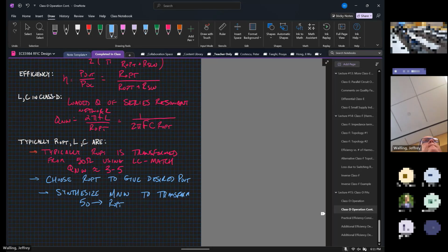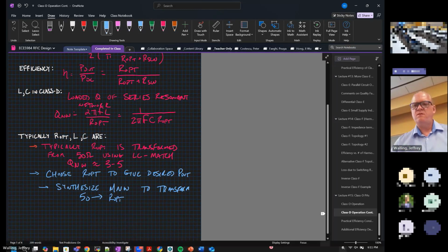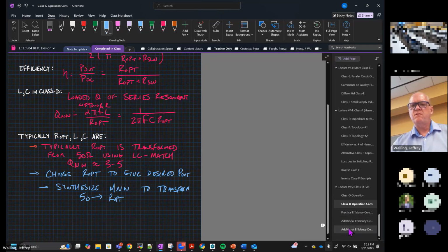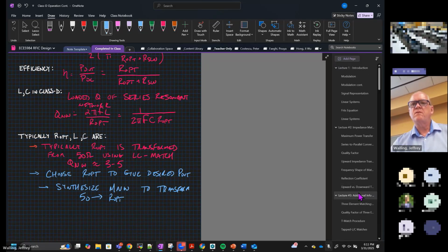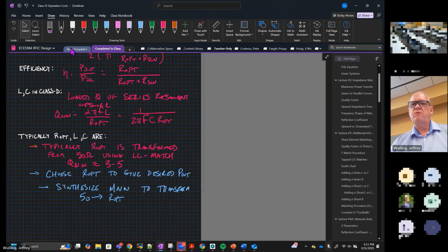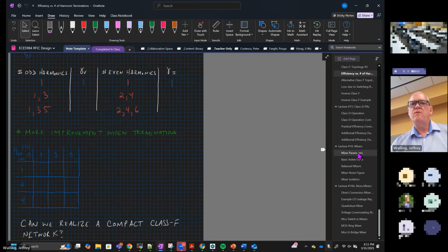Yeah. So while we were doing the LNA homework, in the tutorials you mentioned, I don't know if we talked about this, but the self-resonant frequency of the inductor was not considered. Setting 15 gig as the minimum operating frequency at 5K or 6K. Is there a rule of thumb that we use, like less than a third? Well, let's see. Let me make a sketch. Because that seemed to limit the Q more than anything else that we've chosen in practice.